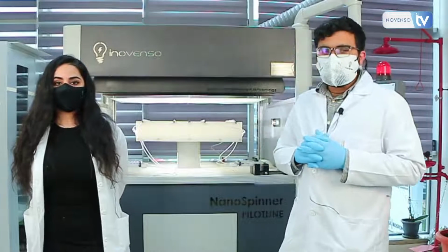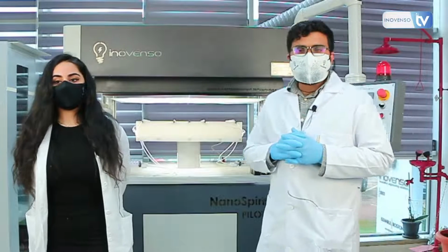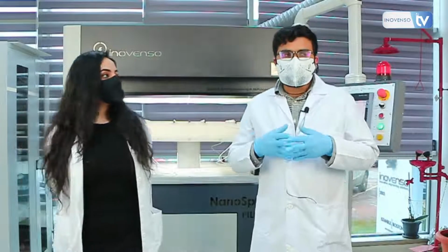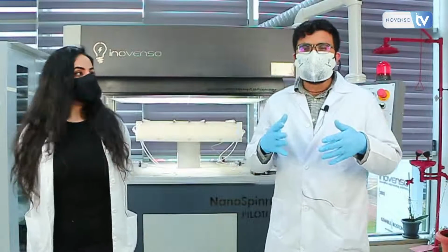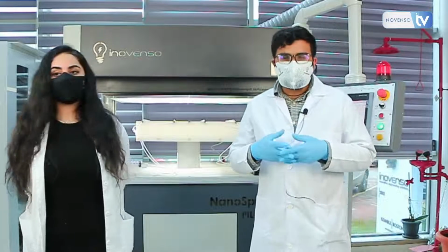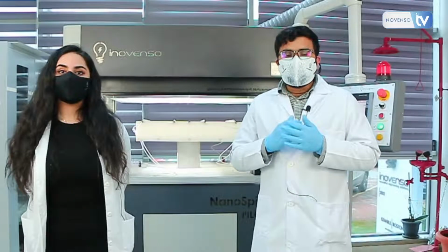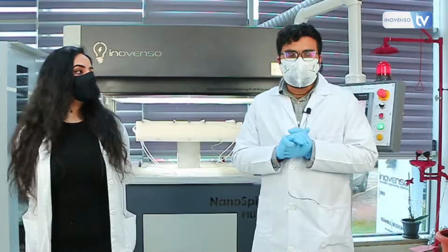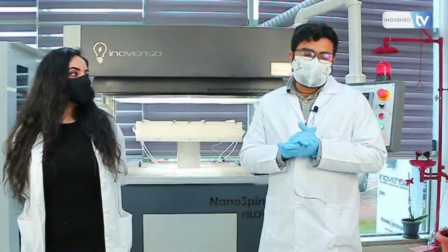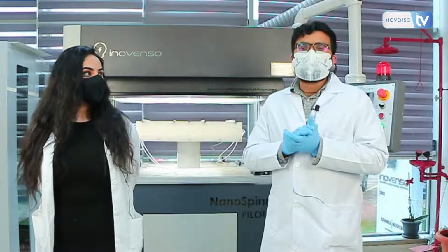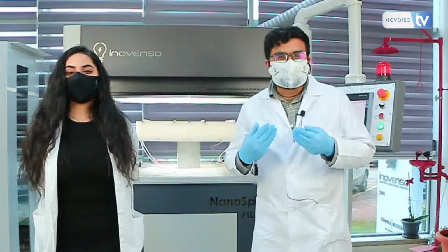Right, so I should probably talk about some of the standards, such as the EN ones. We have results for EN 143 and 149, which are basically the European standard for face masks, but I believe the American equivalent would be NIOSH. We have Nelson Lab ratings for certain parameters. For air filters, there is of course the ASHRAE 52.2, which differs a bit from the EN 1822 and the EN 779, which I believe is now defunct. They're more or less testing standards, and we are more well acquainted with these results for our air filters.